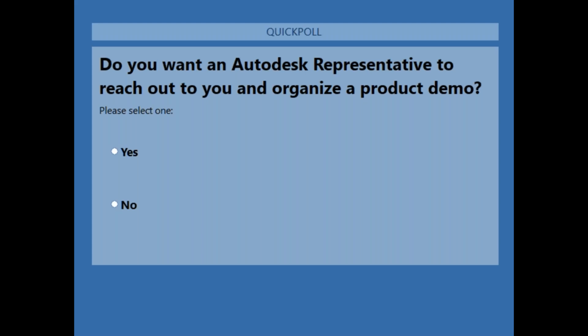There's a question as to why Plant 3D requires some sort of support files before opening any kind of project. Yes, because Plant 3D works on specifications and catalogs. While doing a plant model, you will require all this information to model your plant project. That's the reason it takes into consideration all these specifications and catalogs in the background. Again, coming to a central file, we don't have a concept of a central file. We could divide your plant project into zones and work on that particular piece of the project.